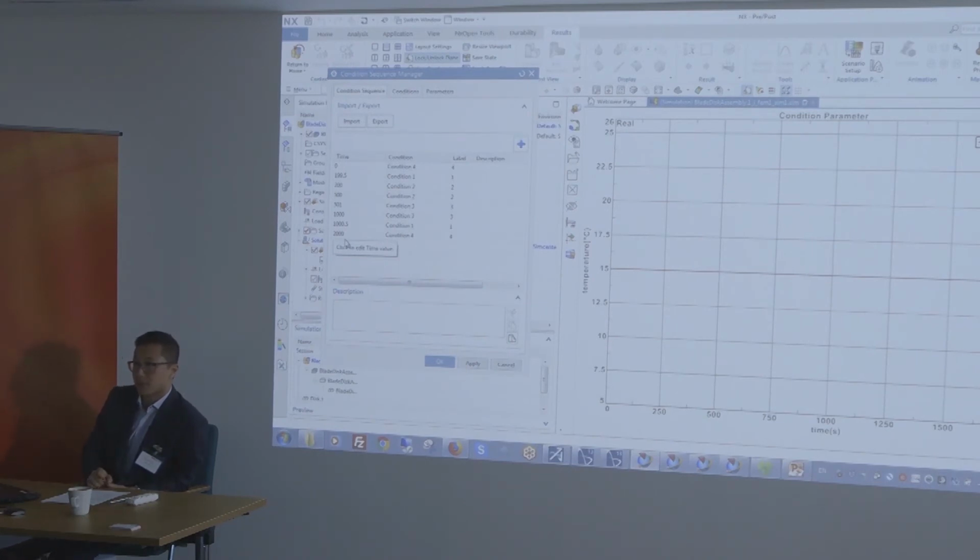And there's also a nice feature in the flow solver. Once you've reached steady state on the flow side, although you may not have reached steady state on the thermal side, you can freeze the flow field. So you get an accelerated transient, coupled response. That's called freeze flow. And we can direct you to that.